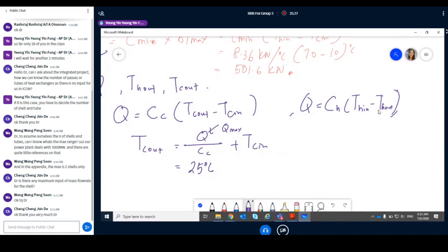But we haven't gone to the real case. This is just the limiting case. So students, there is a discussion slide over here regarding this example. We look at it. Hot water is cooled to the limit of 10 degrees C. Meaning that this hot water, so TH out, is close to 10 degrees C. This 10 degrees C is actually the inlet temperature of the cold stream.